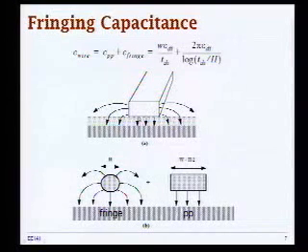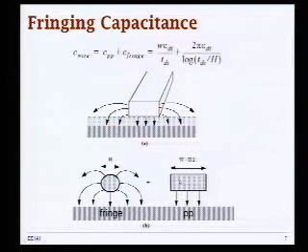component. And then you can simply analyze the impact of both by decomposing your wire into two equivalent capacitances, one of fringing capacitance of a round metal line and another of rectangular line that you get only parallel plate capacitance from.